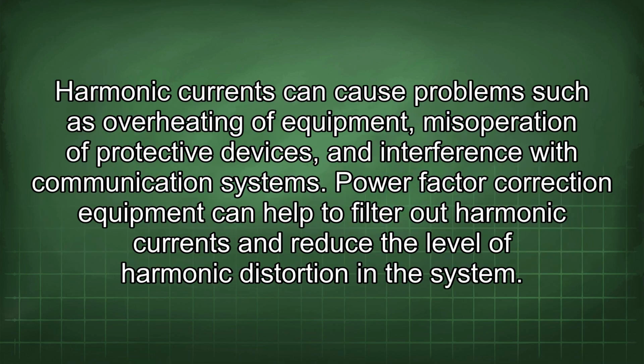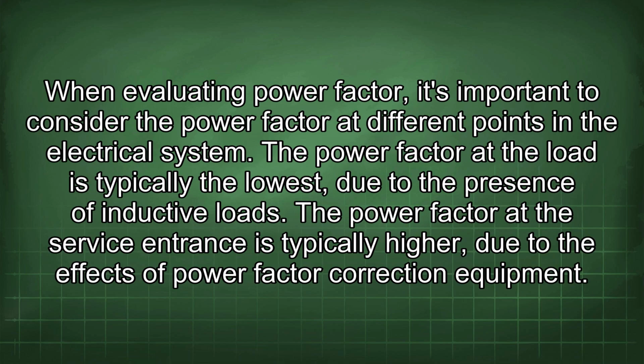Harmonic currents can cause problems such as overheating of equipment, misoperation of protective devices, and interference with communication systems. Power factor correction equipment can help to filter out harmonic currents and reduce the level of harmonic distortion in the system.